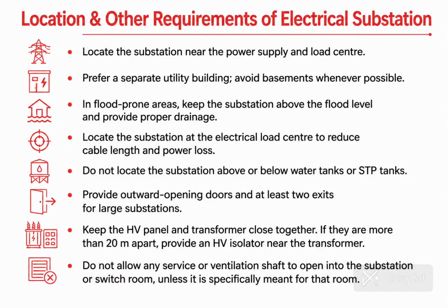Before starting in substation planning, first we should check the availability of nearby power lines. There we have to keep the substation, and the preferable and ideal location of a substation is at the load center of the building. Then the second point is prefer a separate utility building.